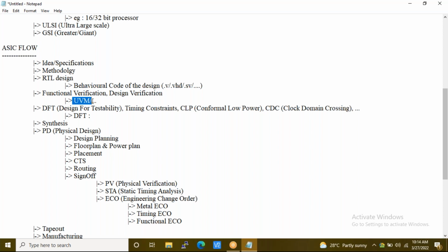Okay, by using multiple test vectors. And when we are talking about the DFT stage, you will be hearing about some functionality checks like stuck-at-0 fault, stuck-at-1 fault, JTAG, MBIST flow. Like that, you will have different sets, which again are used for checking the functionality of your design only. Okay, here using a concept called scan chain.